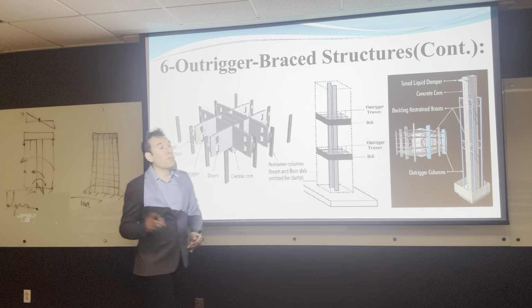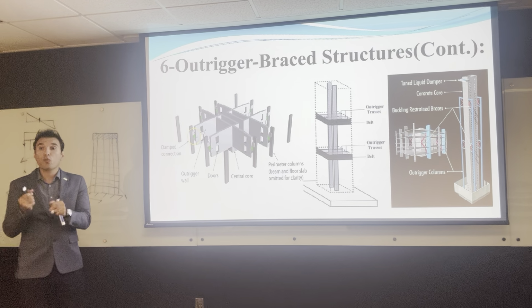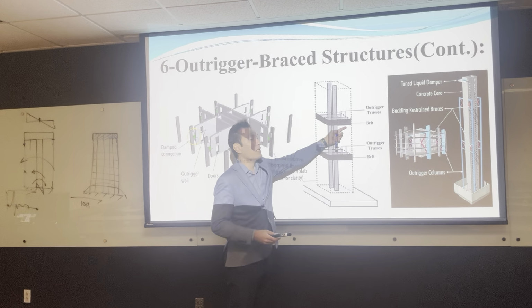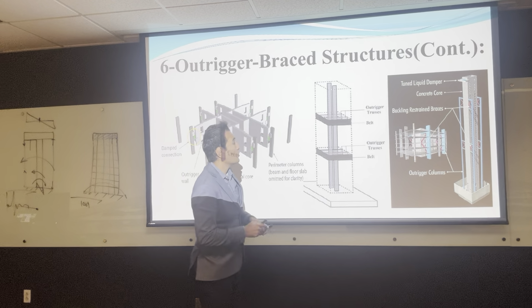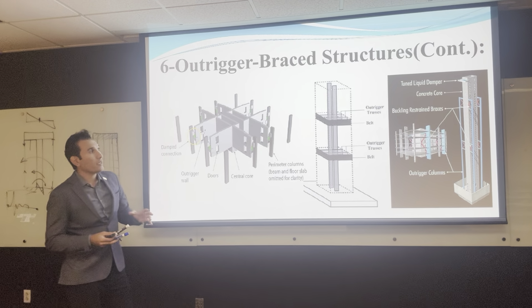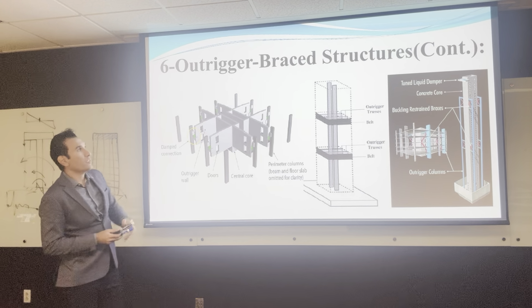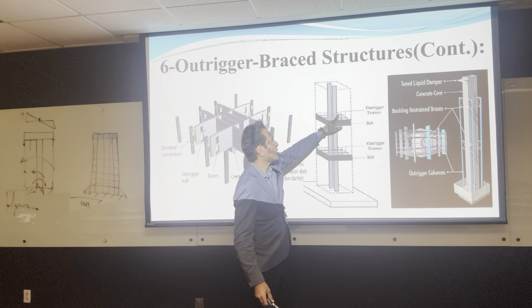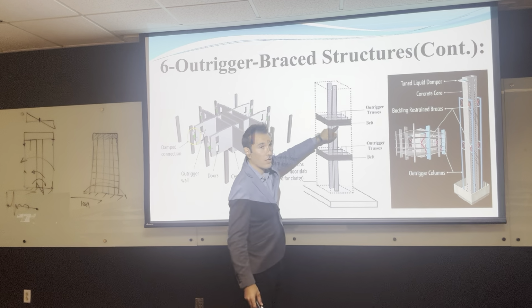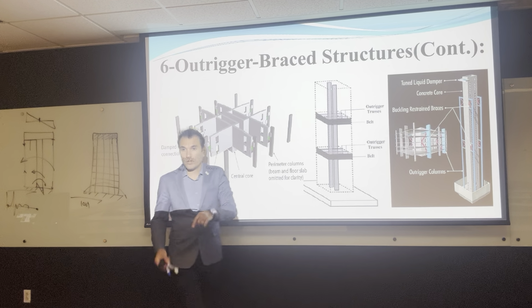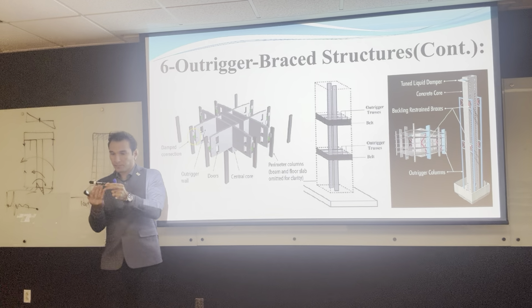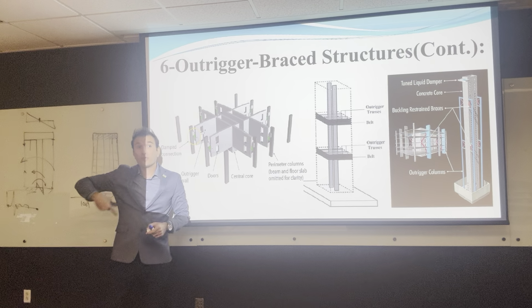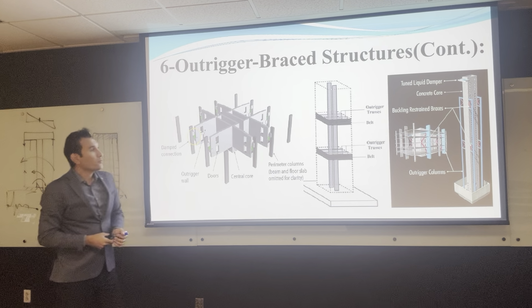But they work better if there is a shear wall holding them in the middle, okay? But it's okay to put them and connect them with columns, all of them as columns. So what are the options that you have? Let's say you have 2 shear walls. Here, he put an outrigger here and an outrigger here, and made a belt of outriggers around them. So the outrigger is the one inside that connects the shear wall with the columns, and the one on the perimeter, we call it a belt. Okay, so it's something like this.